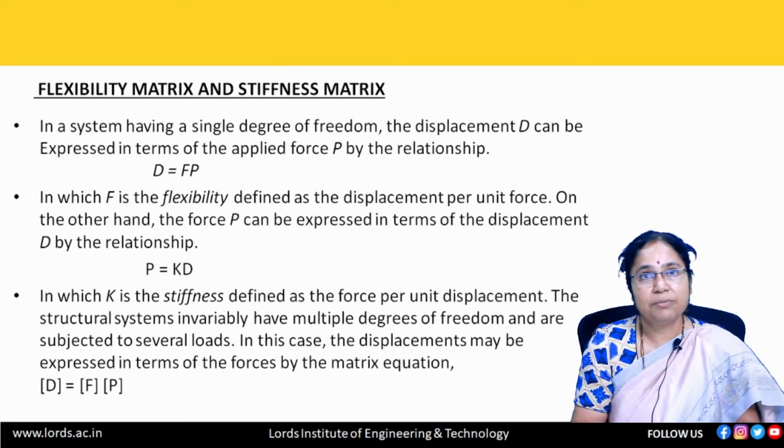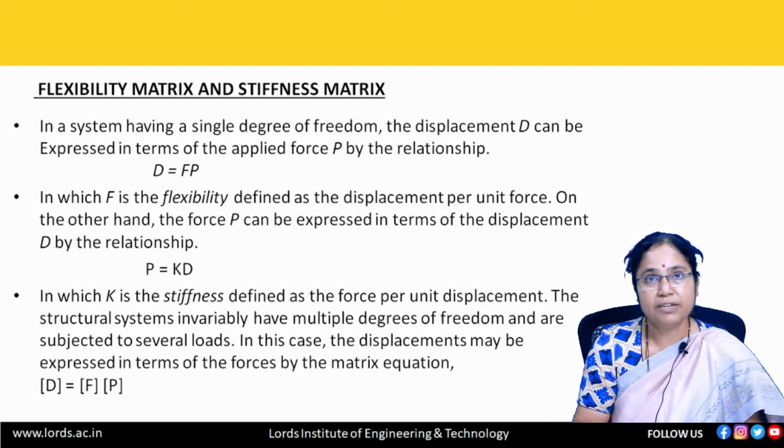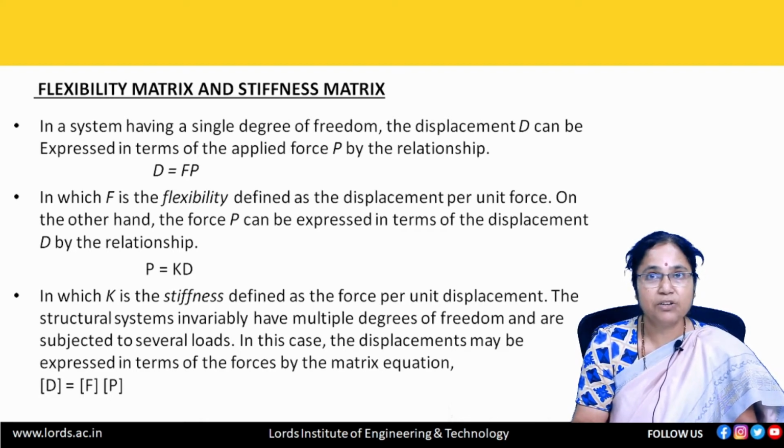Coming to the flexibility matrix and the stiffness matrix, in a system having a single degree of freedom, the displacement d can be expressed in terms of the applied force P by the relation d equal to F into P, in which F is the flexibility, defined as the displacement per unit force.